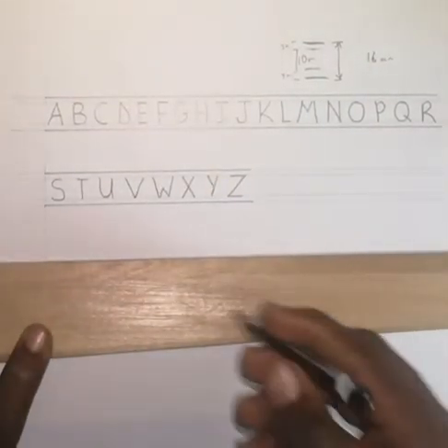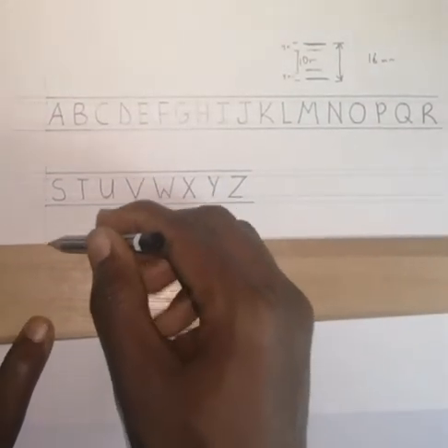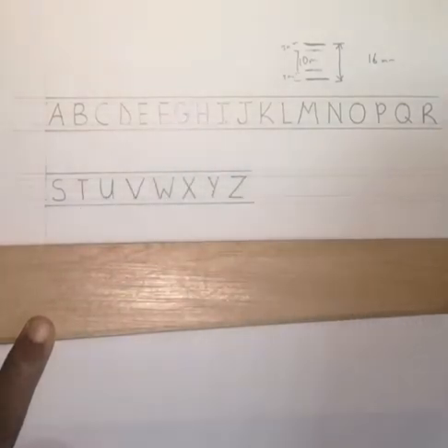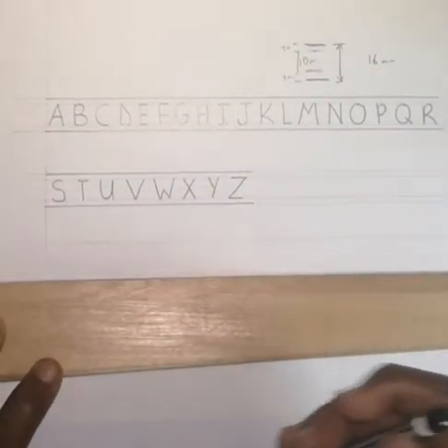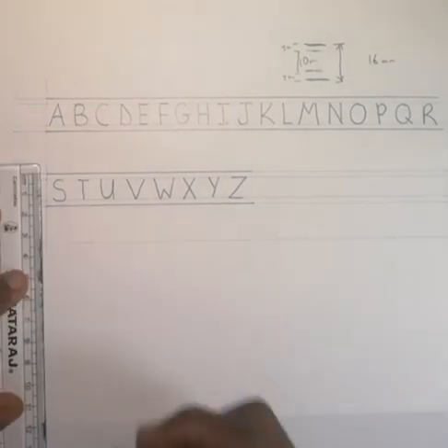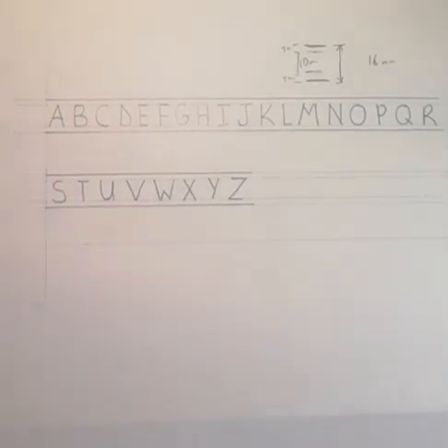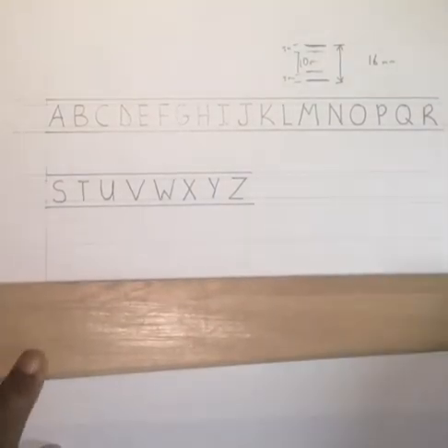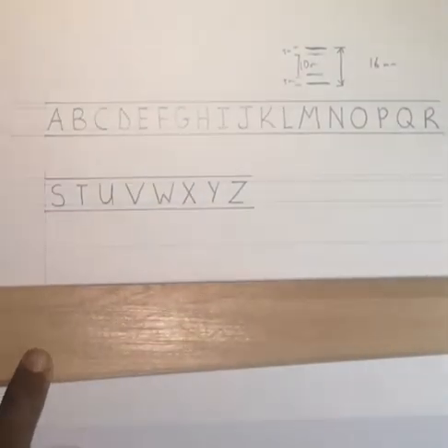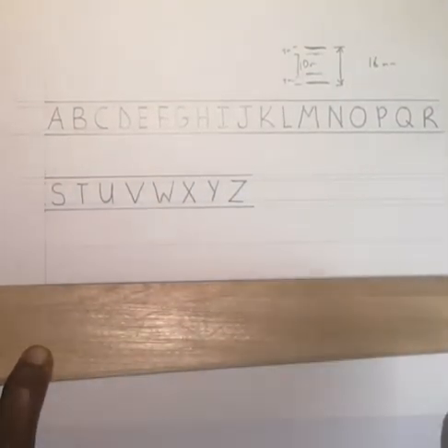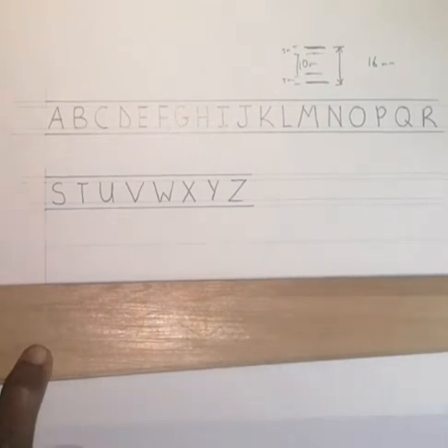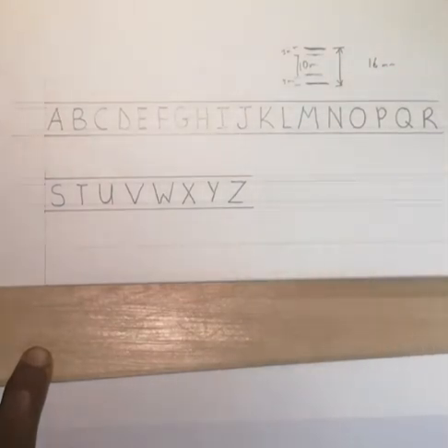Then you would go ahead to also number below. So take note. You can see I always draw thin lines first, then I use thick lines. This is the best and easiest way to draw, because if you make a mistake when you draw a thick line, as I've said, you would have problems with erasing. But if it's a thin line, you just leave it.